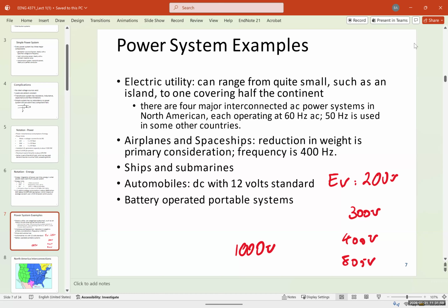But in this range, even small normal transistors and choppers, what we call chopper DC, it's very easy for them. So 400 hertz, 50 hertz, makes no difference for that switch. But if it goes above 10 kilohertz, 20 kilohertz, then it's going to be an issue. And we usually don't go above that for power electronics. Those very high frequencies are just for communication systems. We will barely go above 2-3 kilohertz for these, and it could be done with any.